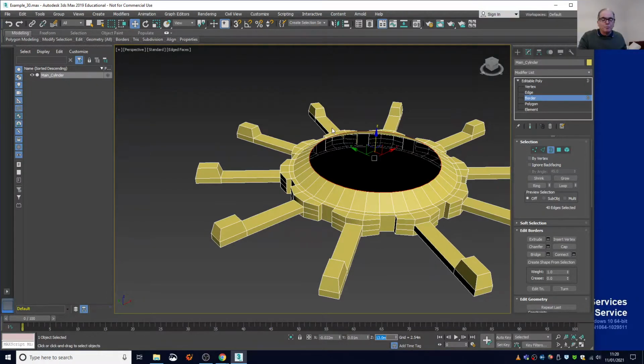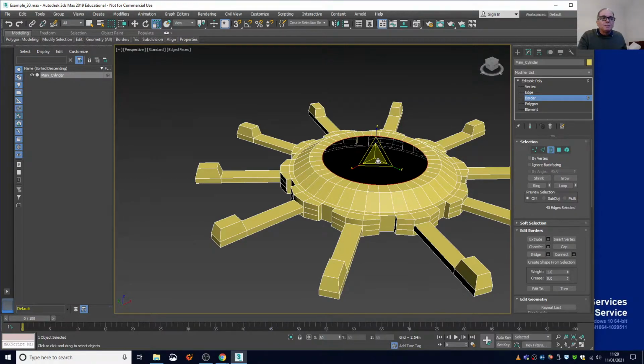So we go to the scale, we press the shift key because we want to copy, we shrink it, we reduce it by 80%, here we are, we've done 80%, and then we move it up by, sorry, by 3. So instead of adding 5, we add 3, so it becomes 16. Doesn't matter actually if you make a little mistake, it's not going to kill you.